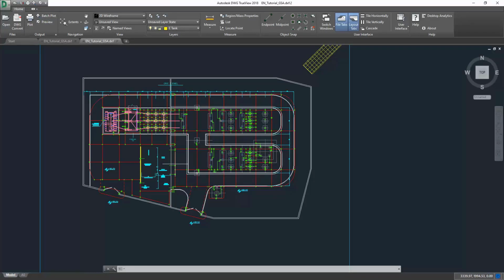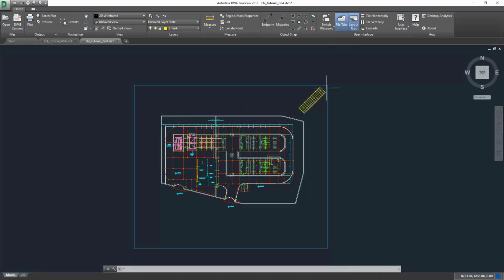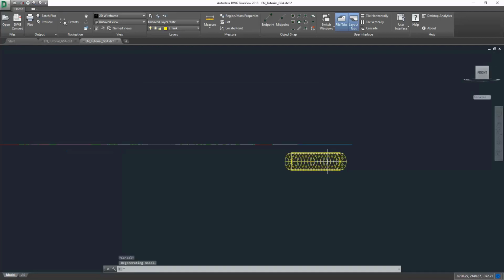You can find the DXF on the XGSLab website and download it from there. Here is a grounding system. Shown in red is our grounded conductor that is inside the substation that's surrounded by a non-conductive masonry fence. Outside of the substation, we have a buried tank. And what's interesting about this drawing is the tank is drawn three-dimensionally, while our substation grounding layout is drawn in a more two-dimensional, common CAD approach when doing a grounding system layout.